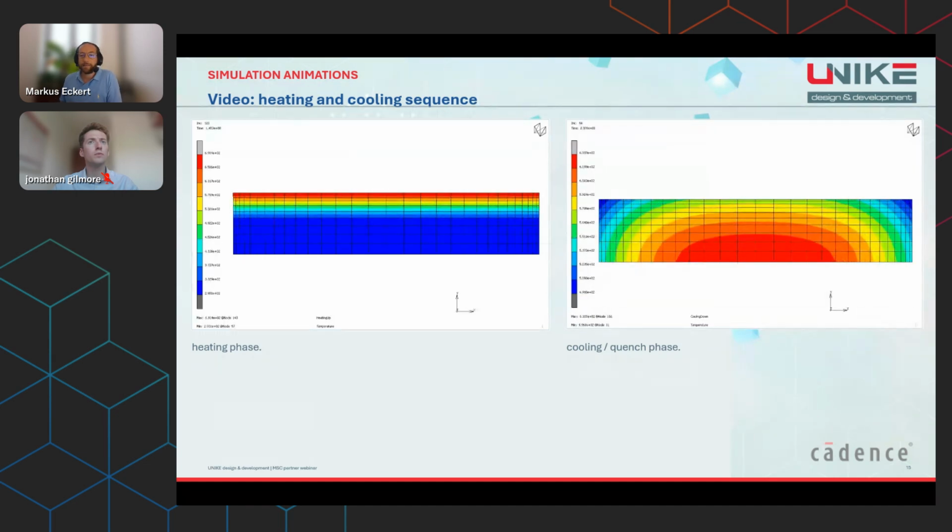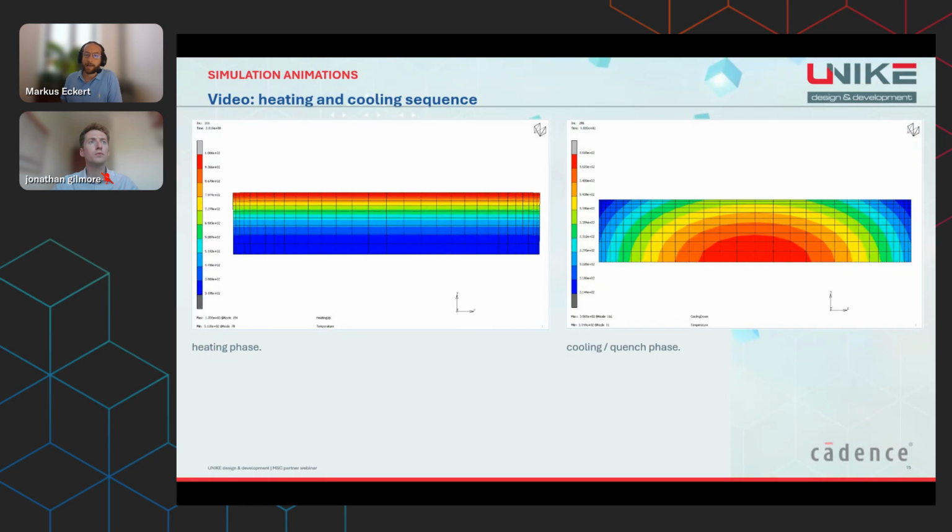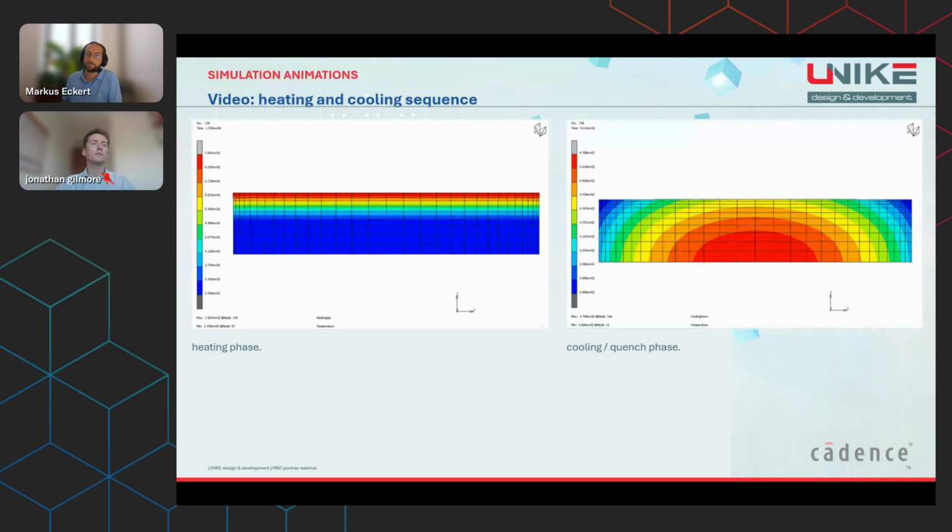The slide is intended as a visualization of the transient chain. In a heating video, we can see how local the energy input is at the beginning and how the heat then spreads through the workpiece. The dynamic behavior matters because the target zone is not just a position. It requires a certain thermal history.